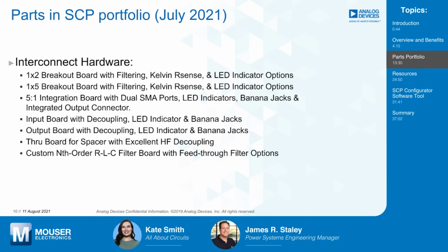And once we had them, we thought about the parasitics involved and also what we wanted to accomplish with those boards, since it was a large chunk of real estate in terms of PCB. So we threw on features like you can add filtering. There are some sense resistors there with Kelvin connections, so you can measure individual branch currents if you want. We put some LED indicators there. They're bidirectional LEDs, so if it's red, it's positive. If it's green, it's negative, or vice versa, I should say.